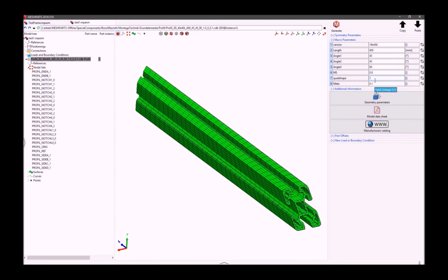Fillet is the parameter that controls the minor details of the model. Sometimes the geometry of the model has little segments of curvature. Those lead to finer elements in the neighborhood. These curvatures often generate from the rounds and fillets of the geometry. We can vary this parameter and control what should be the smallest curvature allowed in the model. Here 0 means no fillets or rounds will be removed, and 1 means all fillets will be removed.